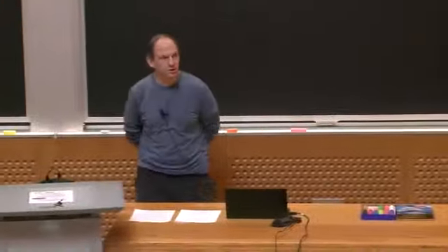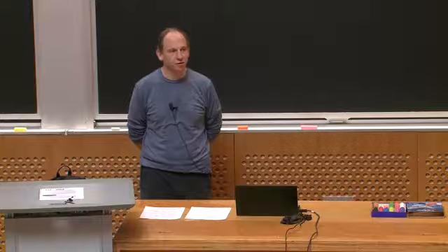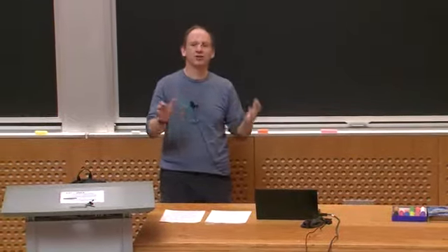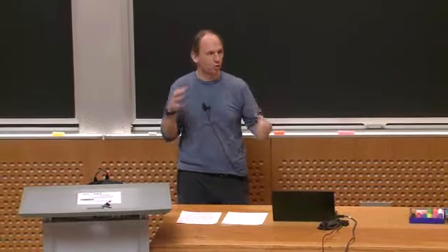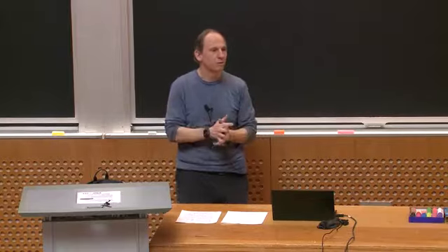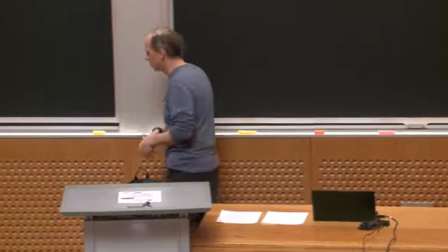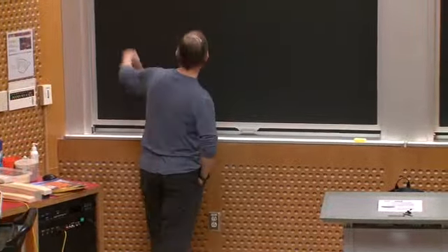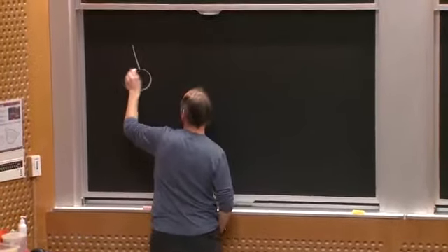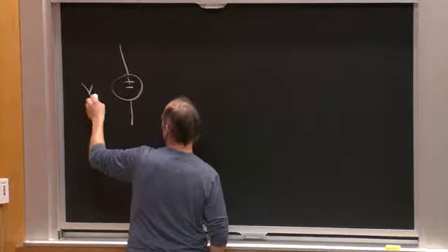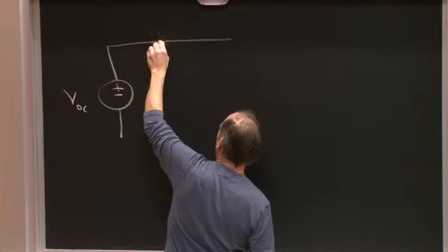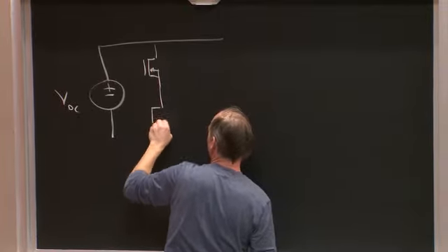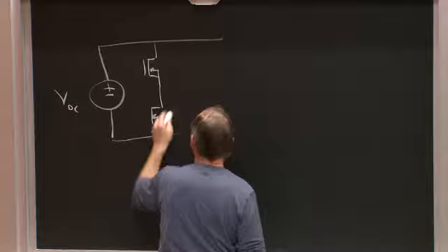So what I wanted to do is continue the discussion of inverters that we started last time. And what I'm going to show you are some expansions on the way you can think about controlling the inverters to get better performance out of the waveforms. So we introduced the basic voltage source inverter structure, which is 4 switches. Very typically we'll use bidirectional conducting, single directional blocking switches like MOSFETs, like this, for example.